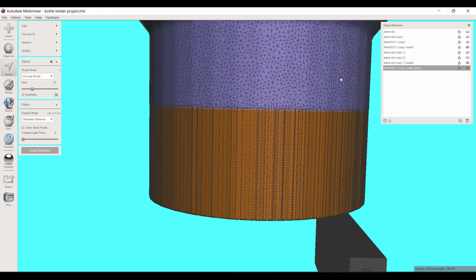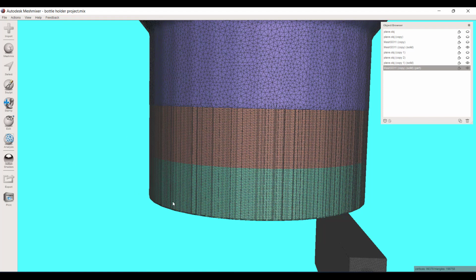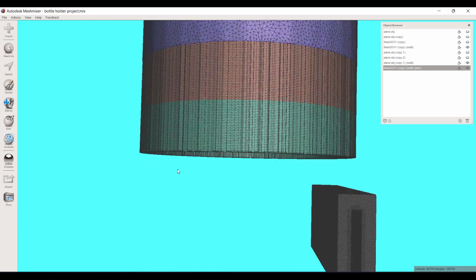And the hotkey for that is hold shift, and then click your left or your less than sign. And I'm going to go down to maybe halfway on this and then just give it a try and see what happens. All right. Now while I've got that, I'm going to hit Control G, make a new face group so that now it can just be clicked on.